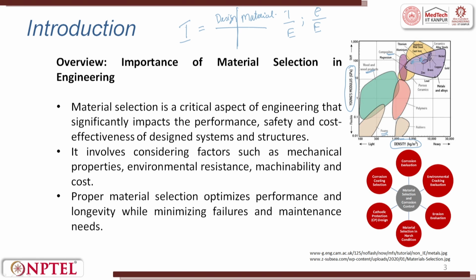In material parameters also, many a times you will have 1 by E or you will have something like rho by E, right. So, these are all in the formula you can see for I channel or I beam, how do you calculate moment of inertia. So, there material properties whatever is there can be extracted from this curve. For example, density versus E in the formula if it comes. So, from this graph you can get, and now we can also try to figure out whether it has a relationship of 1, a relationship less than 1, greater than 1.